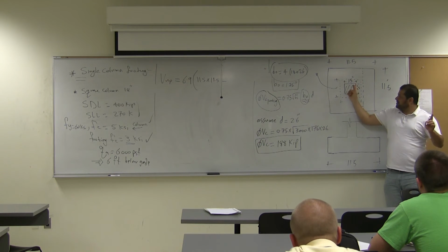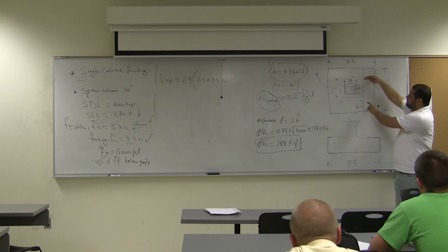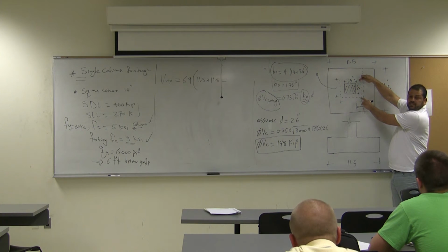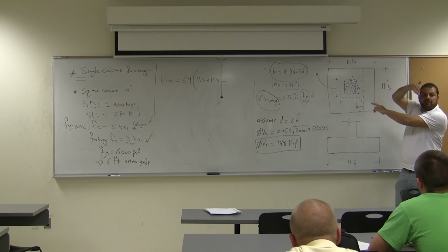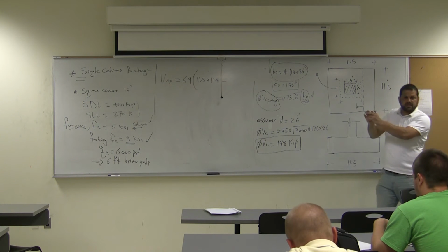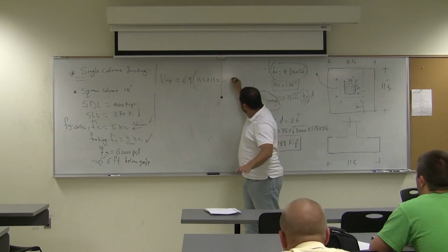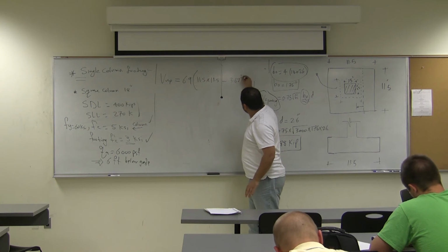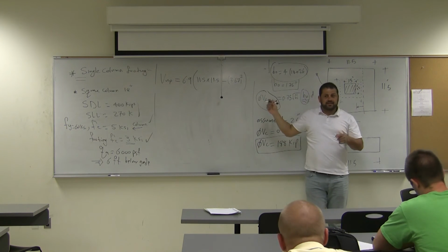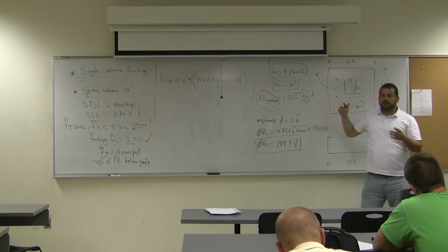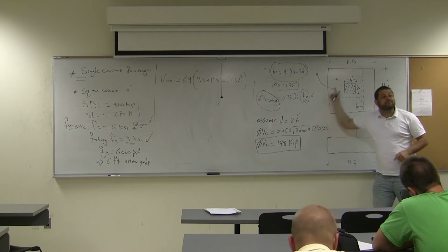It's going to be 18 plus 26 squared. What's this side? We said 18. 18 plus 26, so 44 squared. That's in inches, so we divide by 12 to get it in foot. So how much is that? 3.67. Minus 3.67 squared. You understand this? In there we get the area. For the punching force in here, we get the perimeter.